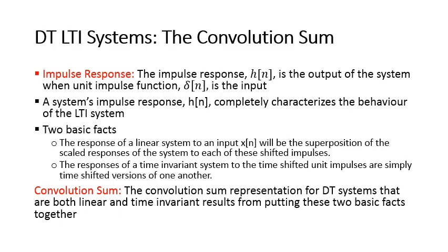The next topic we are going to revise is the convolution sum, how to find the convolution sum. To find the convolution sum, recall that we must have an LTI system, and LTI basically is a linear time invariant system, right? The first thing is the system must be linear. A system is said to be linear if it holds two properties, superposition and scaling.